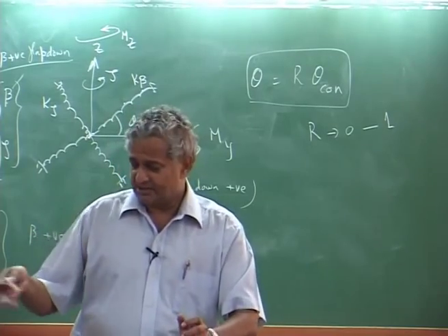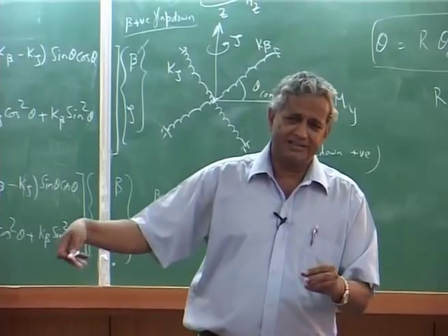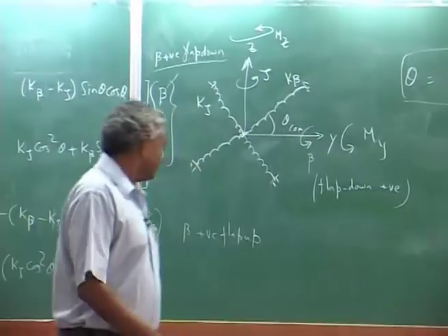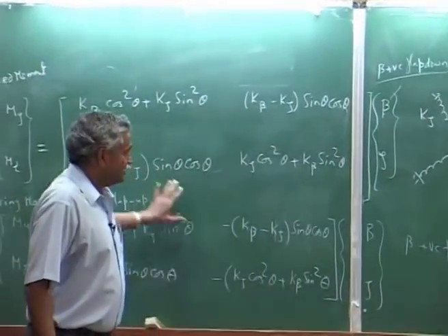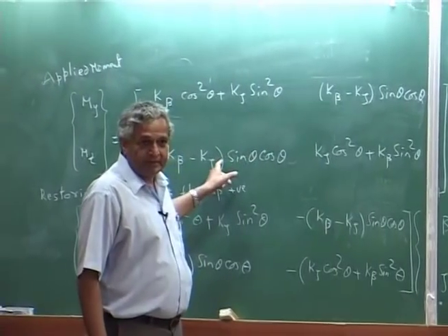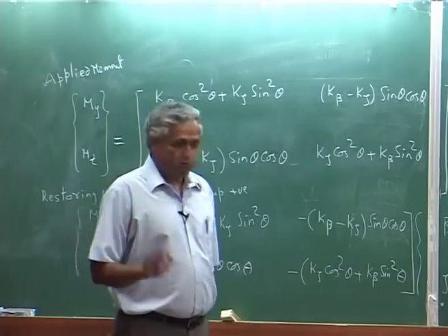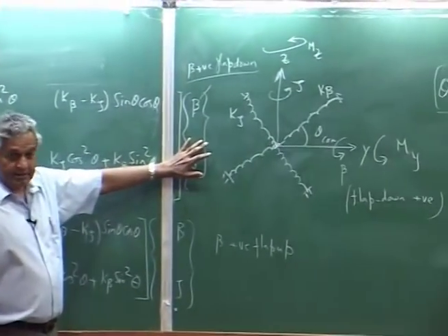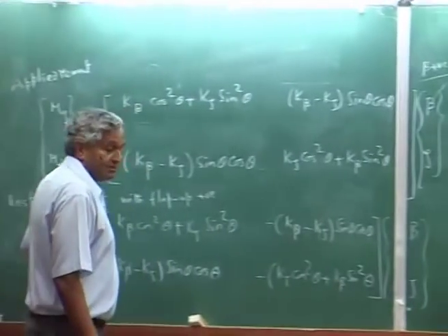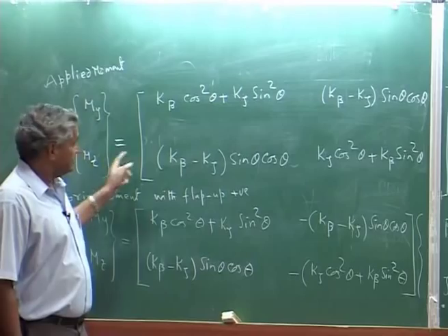I give a rotation, it need not go faithfully, full rotation need not go, there can be a slight decrease. The interesting thing is, if you look at the coupling term, suppose I have only flap motion, I do not have lead lag, then automatically I get a lead lag moment because of this.